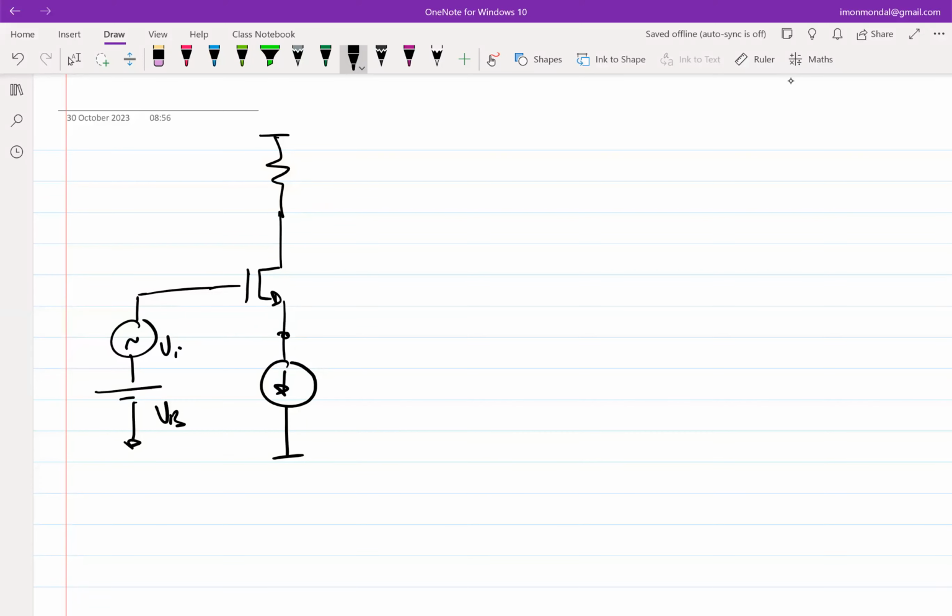And then we saw that if we only keep it like this, what will be the incremental current through the transistor? Zero, right? It's a constant current source, which by definition means that current cannot increase. So incremental current is zero. So if we take the output from the drain of M1, it will be zero. So this is by no means a common source amplifier.